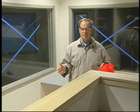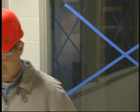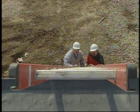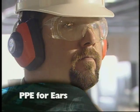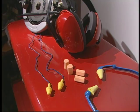Personal protective equipment, also known as PPE, is the construction worker's best friend. PPE protects you from all kinds of job site hazards, including those that come from processes you perform, the environment, and irritants. There are several types of PPE. Each protects a specific part of your body from harm while you work. Hearing protection protects you from exposure to high levels of noise that can cause temporary or even permanent hearing loss. The most common hearing protection devices are earplugs and earmuffs.